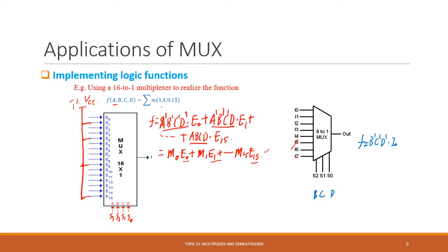For the others, we also don't forget to configure them, because we have to make those terms 0, right? So we need to fix those data inputs to ground, which is logic 0. That's how we realize the function.